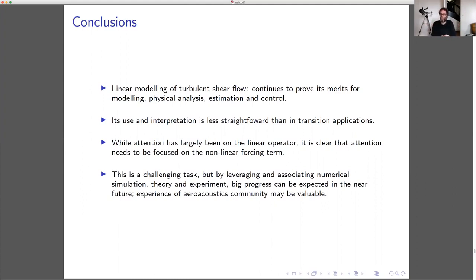Then you have issues associated with the grid on which you store the data. Very often you have interpolation, which adds interpolation errors. We're discovering that there are issues associated with aliasing because the forcing term is something which is a d/dt of the state variables, and so you've got a multiplication by frequency. So the forcing quantities have a much higher frequency content than the state variables, which means that what you would have accepted as a good sampling frequency for a correct spectral description of the state variables is not sufficient for the forcing. So there are a number of practical issues which are making this forcing term extremely difficult to extract from high quality large eddy simulation. So far, taking it from DNS at low Reynolds number is okay. Finding it at higher Reynolds number is a real issue that we're going to have to figure out.